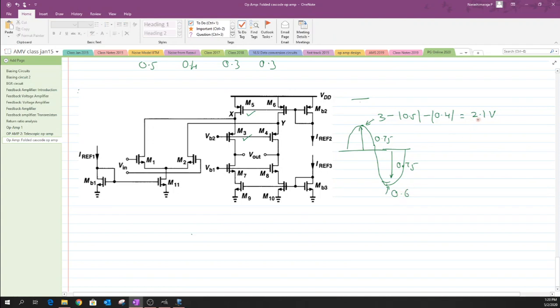And since we want to fix the common mode voltage somewhere between these two extremes, we would add up these two values, which is VO max plus VO minimum, and divide that value by half in order to get this mid value, which would be equal to 2.7 divided by 2, so 1.35. I hope that this is the right answer.